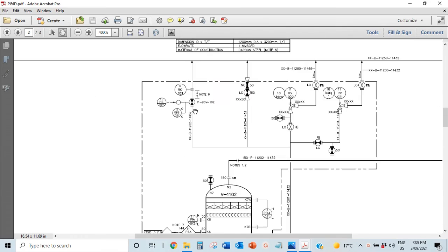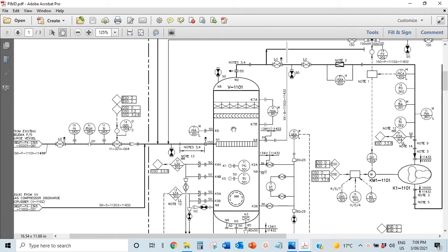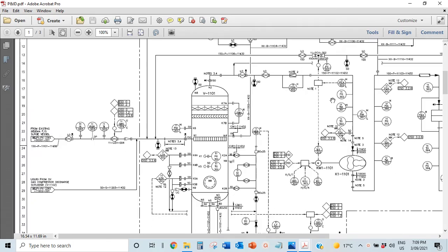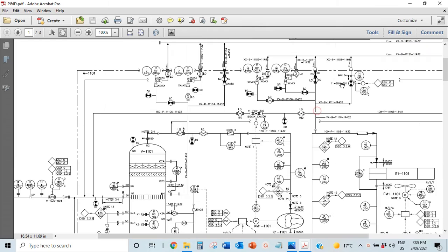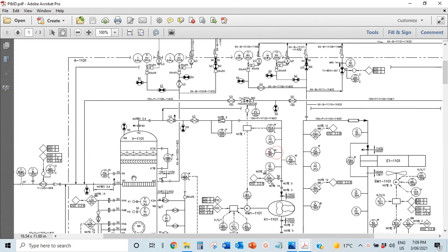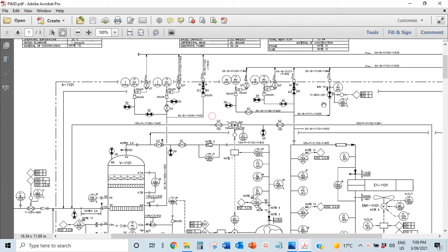They're very important, because what that means is that when there's a fire, you don't have gas trapped in here. You want all the gas relieved, because if you have gas in here, it's a problem, right? It could blow up the vessel. So you don't want to have that gas in here. Depending on how big the fire is, it could cause a lot of problems for you. So you want to make sure that when there's a shutdown, this closes and this opens up, so that you just have dead crude, just dead liquid in here, and all your gas goes out to the flare.